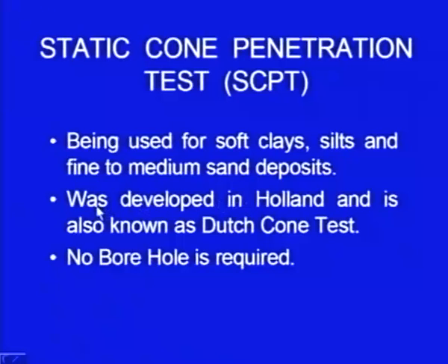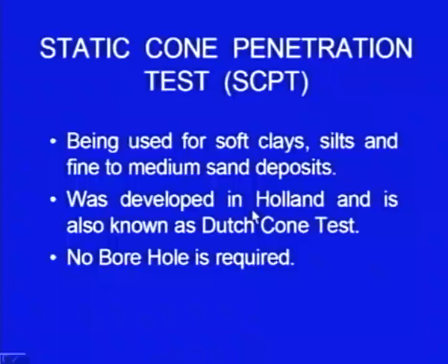This test was developed in Holland, and sometime it is known as Dutch cone test. Unlike SPT, in case of the SPT we needed a borehole. The advancing of the borehole is a tedious job, and here the advantage is again that no borehole is required.